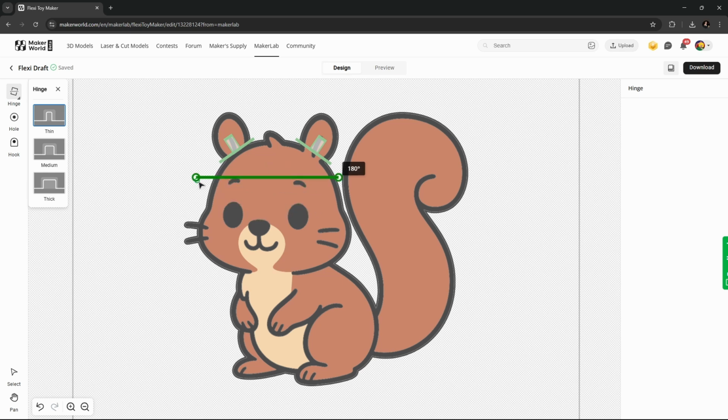If you want it completely straight and you don't want to rely on your hand kind of figuring out where that straight position is, you can simply hold shift. Shift will hold it at north, west, south, and east position. You can see, and you can even get the diagonals, 45 degree, 135 degree. So that's perfect. It will sit on those axes. Okay, so if you're worried about having a lopsided line, hold shift while you drag this line, and there is another hinge placement.